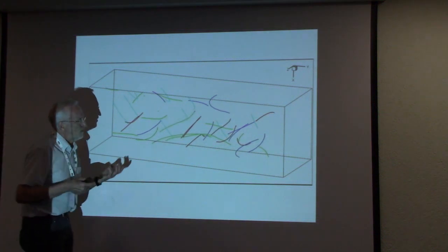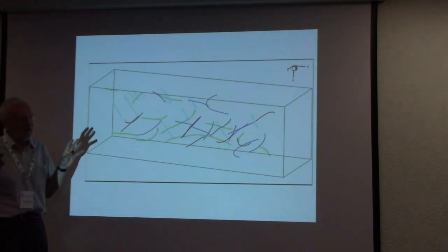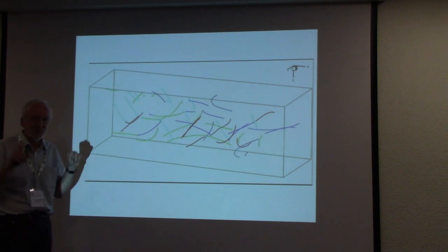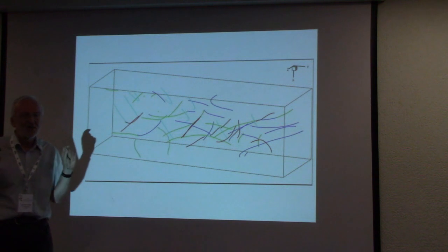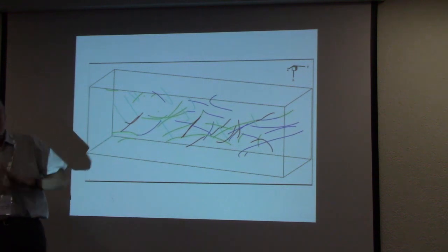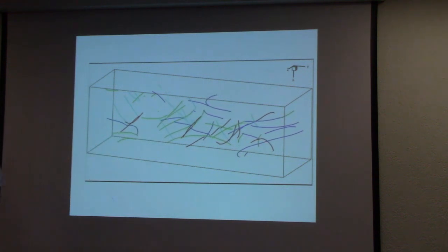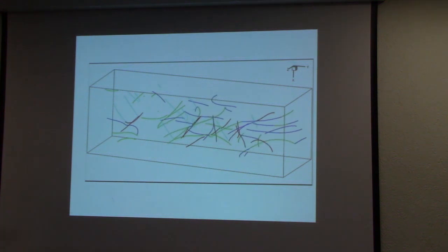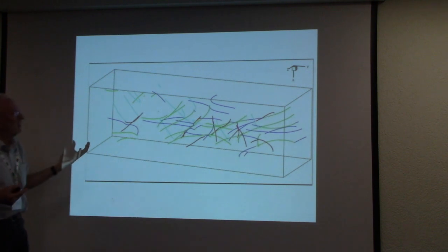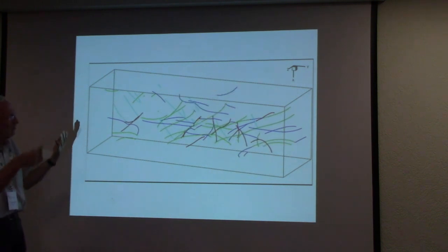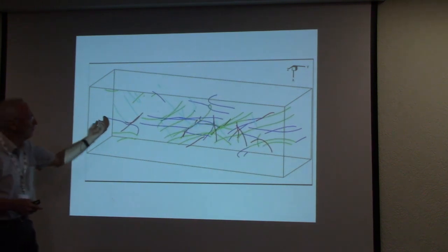In 2D, I thought that you can really realize relatively large plastic deformation, but they do not reflect the real plastic physics. They reflect some of the effect of discreteness of plasticity, but not all. And for this, you have to take into account really the 3D nature. These dislocation lines that we have seen are curved.